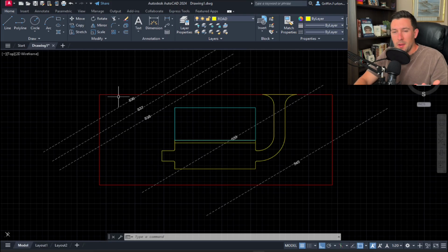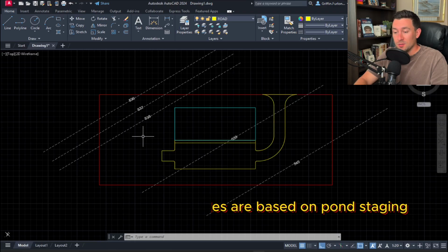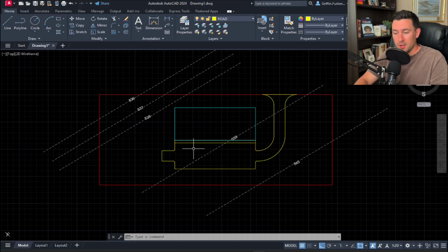The reason I might not want to set a pond on this higher side is that municipalities typically have certain drainage requirements and drainage codes that you have to follow, where you have to set your edge of pavement grades or your building per the design levels of your pond. So the lower you can make these values, the less fill you're going to have to bring into your site. Again, the higher the design values, the higher you have to fill your site.